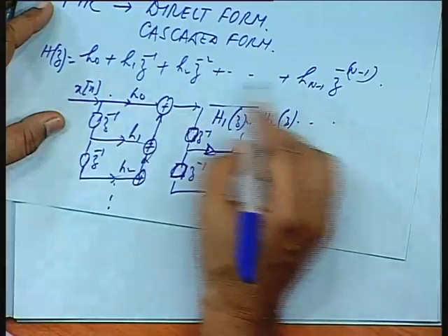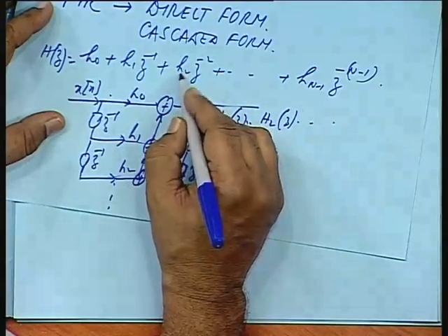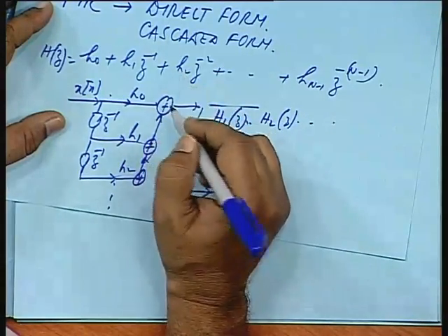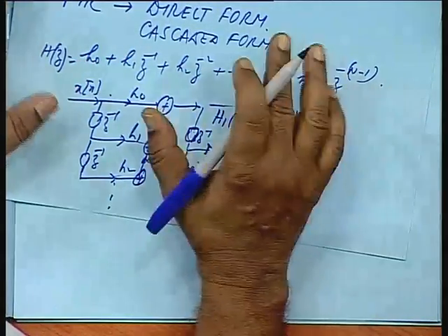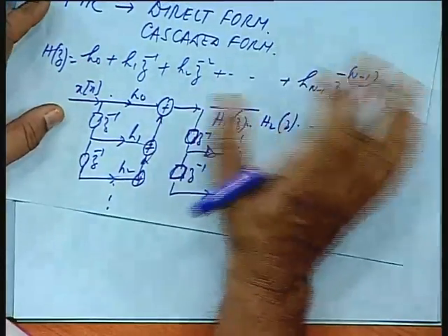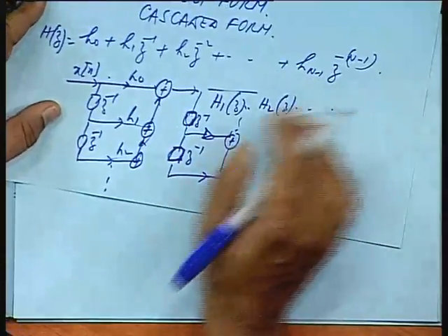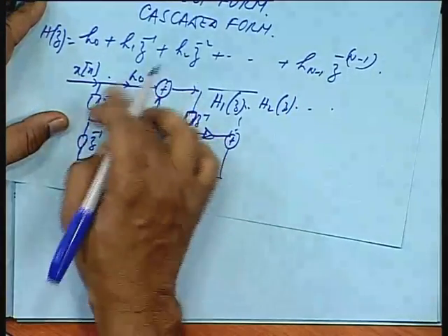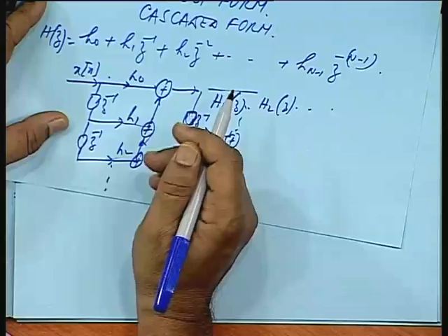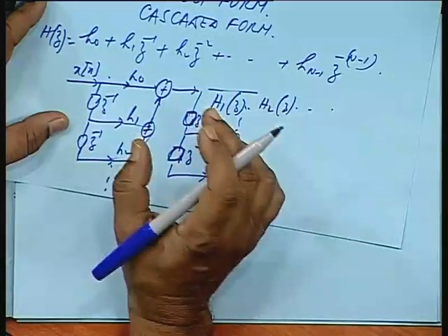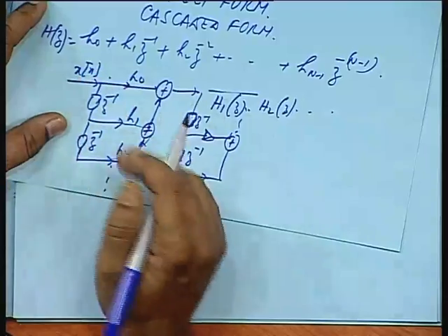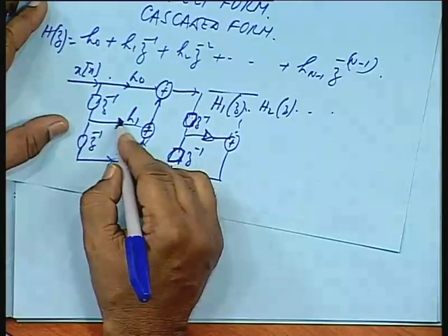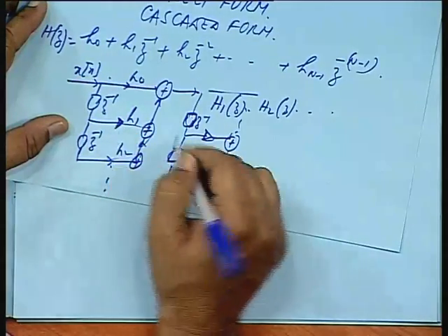Whereas here, if there is a shift in the value of H2, it will affect all the n minus 1 roots, all the zeros will be shifting, okay. Whereas here, only the zeros corresponding to this particular block, this quadratic, will be affected, and it will not affect the others. So, you are going to restrict the movement of zeros due to the drifts in the parameter values.